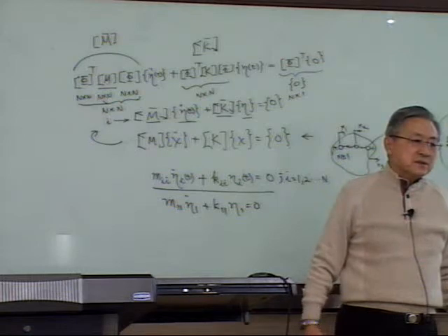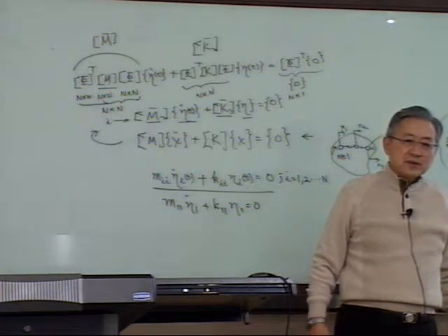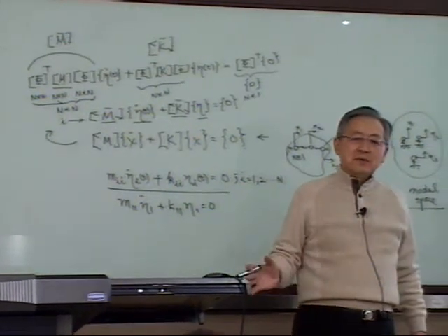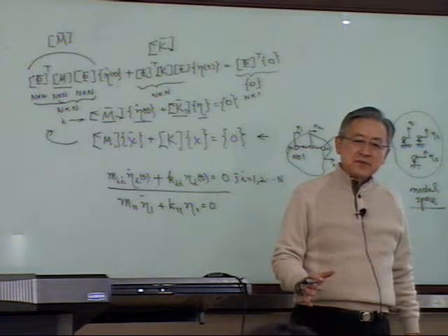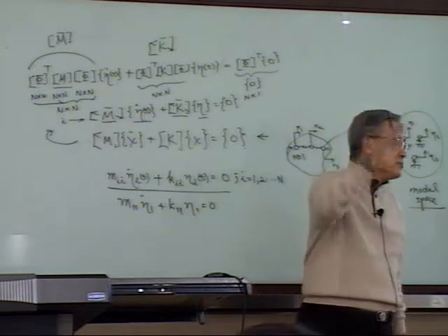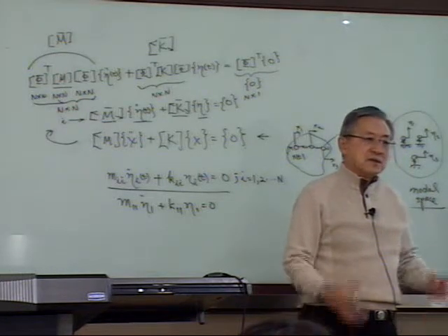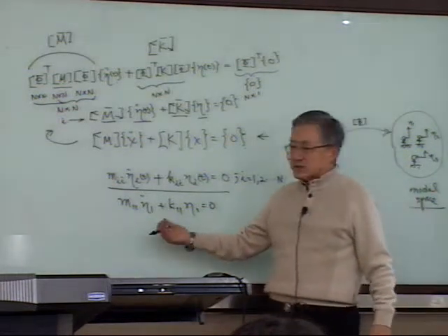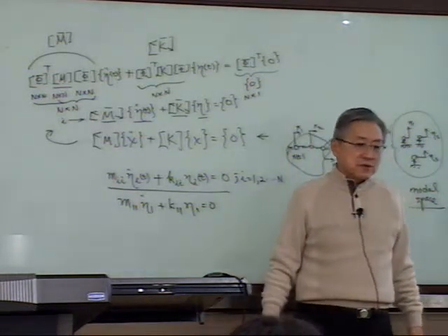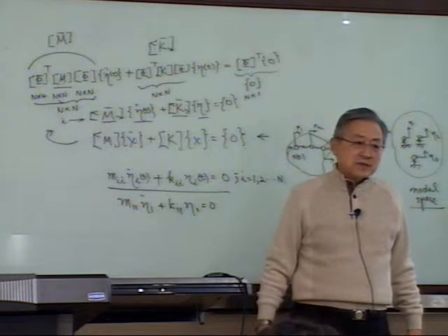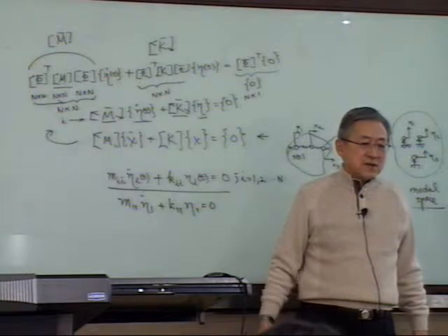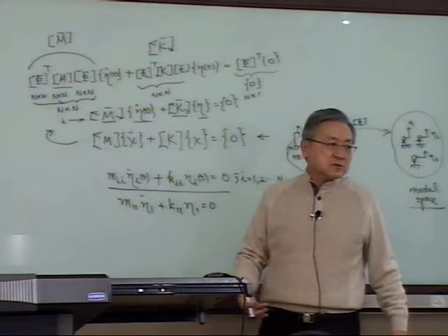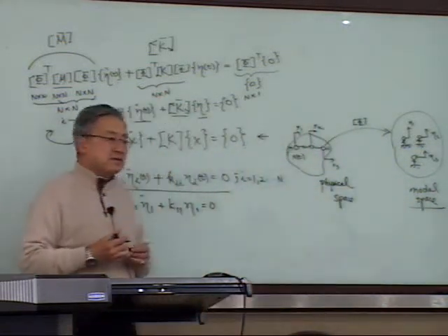It has nothing to do with eta 2 or eta 3. That's one of the reasons to move the system from the physical space into the modal space. Then life is easier. This equation is a second order ordinary differential equation. You did it already, very easy to solve. Only the homogeneous solution is needed, no particular solution, because it's a free vibration.